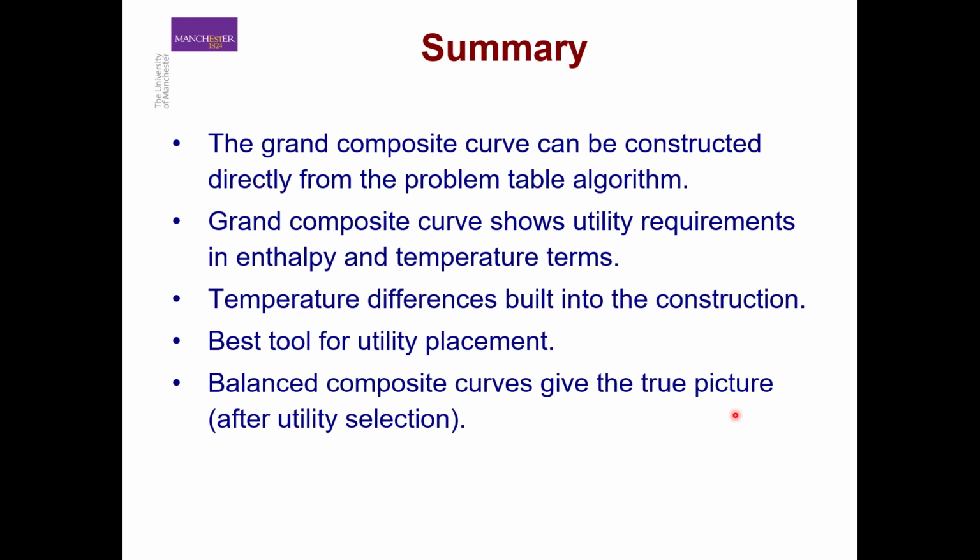And we should be using the balanced composite curve to give us a proper, true picture of our utility pinches and how our utility pinches divide our heat exchanger network design into different design regions. So that is all for this part of the lecture.